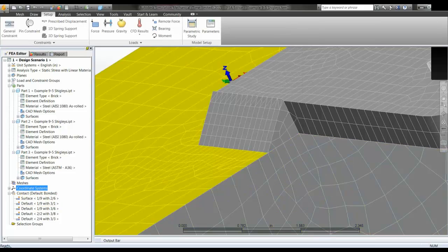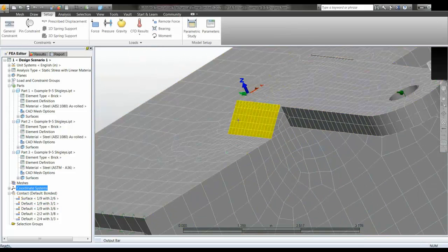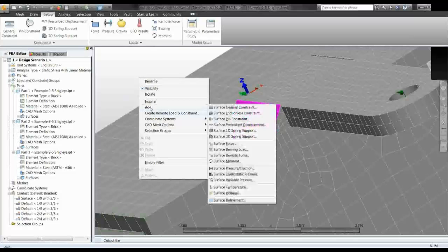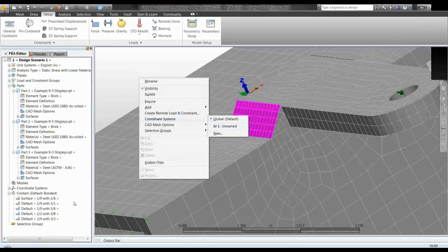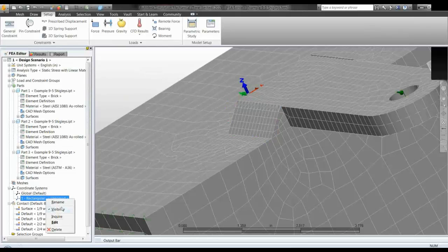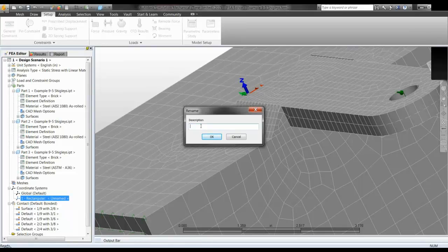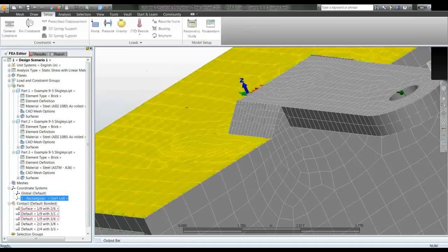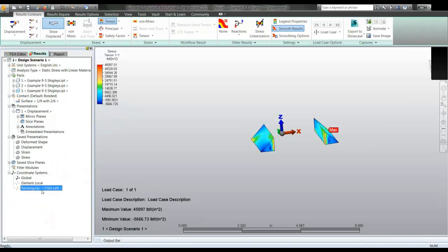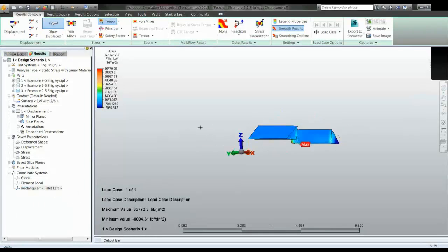We go, okay. So that creates a little coordinate system for this fillet. We then just need to apply, where is it? There we go, coordinate system right here. So it's created. I didn't add a name to it when I defined it, but I can go back and name it. Call this fillet left and go OK. So it should be all I need. So here it is. I can now activate it, and everything will be following that local coordinate system.